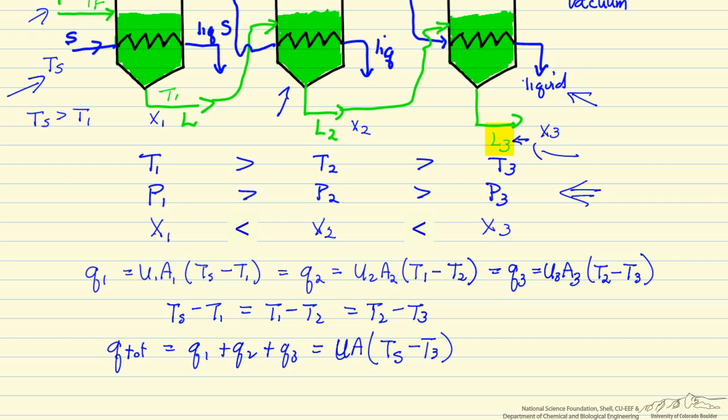It's also useful if the concentrated solution leaving, our product, has some temperature sensitivity as we increase its concentration, and we'd like to operate at the lower temperature. The actual calculations are really very similar to those for a single effect evaporator.